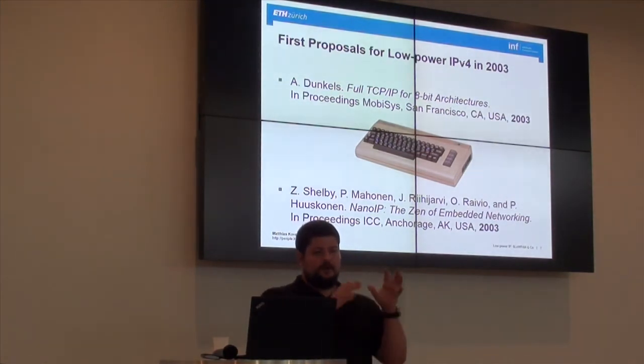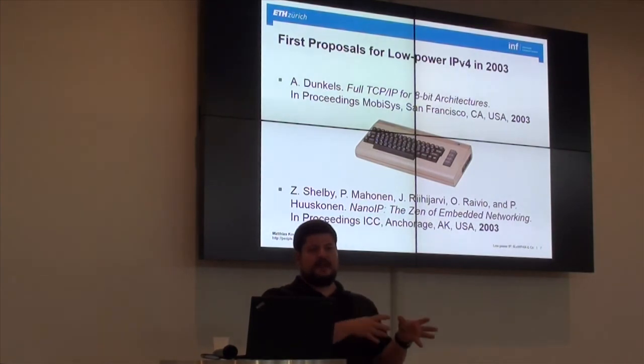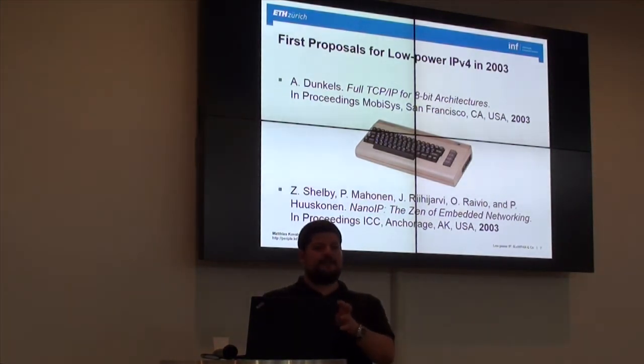So there's this OpenMote, which is basically a company to produce the hardware, and then there's the OpenWSN project from UC Berkeley, and they kind of built the whole stack. So they started from scratch from 6TiSCH, so time scheduling and channel hopping and so on. They have 6LoWPAN in there, and they have a CoAP implementation, and that's in this OpenWSN software stack. I mean, there's also CoAP for Contiki, you can flash on that. TinyOS supports that, you can definitely port this, maybe with some more effort on this platform.